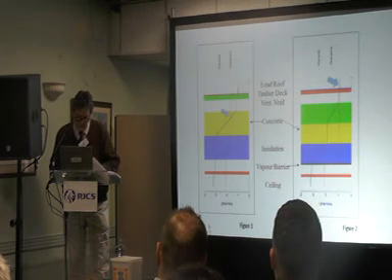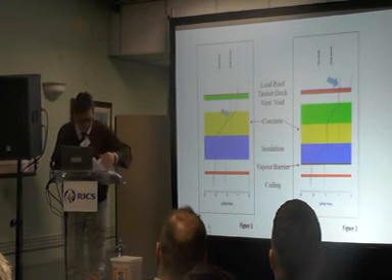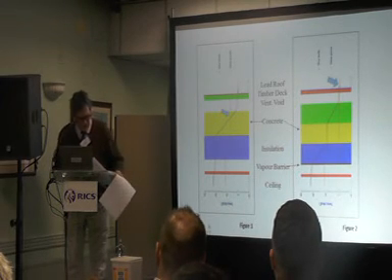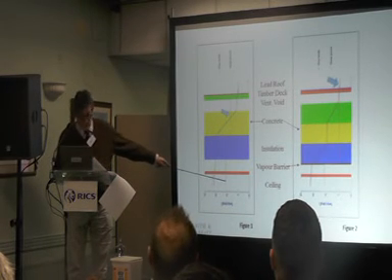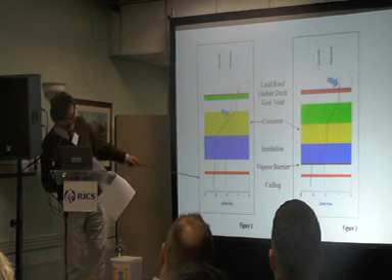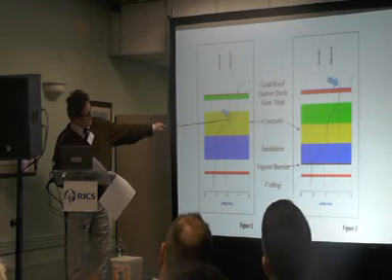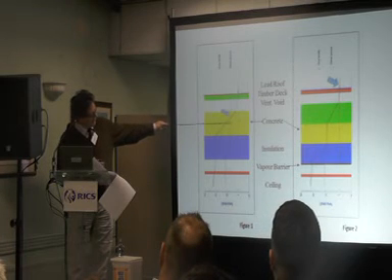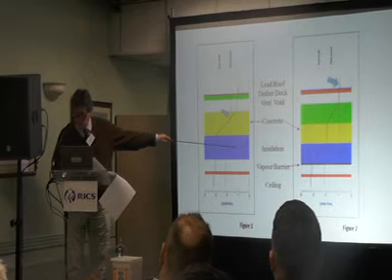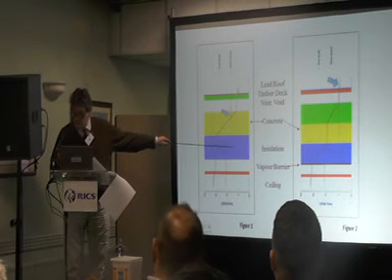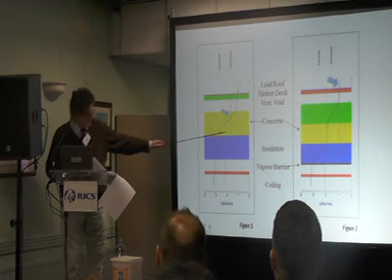Now the difficulty we've got here is, you have a temperature line and an RH, relative humidity line. And here, this is the building before we started, they meet. That's dew point. That dew point is happening in the concrete, and in the concrete is all the steel that's keeping the concrete together. We know that if it rusts, it will occupy 7 times the volume that it did before. We know it will blow that roof to bits.